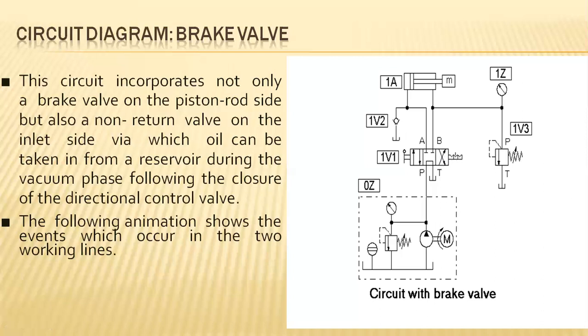Our main motto is to limit the pressure or movement of this piston rod to safe operating conditions. At position 1, let's look at the forward stroke and return stroke by operating this DC valve. When this first plunger has been operated for the forward condition, the first position continues to the force. These are ports number 1, 2, 3, and 4. Ports 1 and 2 will be connected.